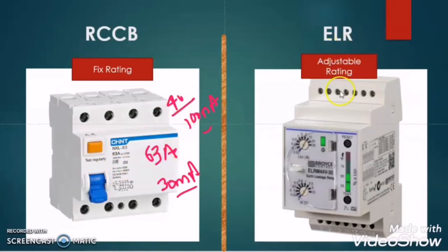But in the case of the ELR, we can change the rating by adjusting this dial. For this example, we can change the sensitivity rating of this ELR from 30 milliampere to 30 ampere. So in a wide range, we can adjust the sensitivity rating of the ELR, which is a very good advantage over the RCCB.